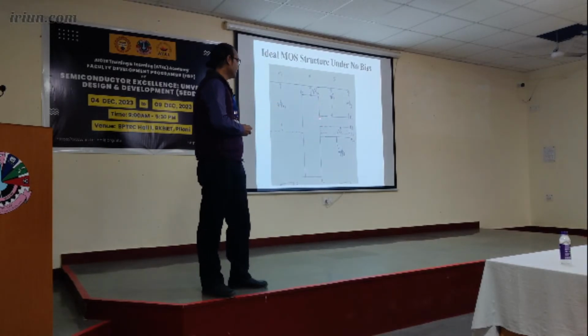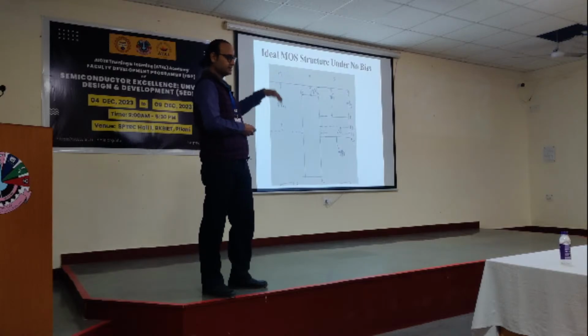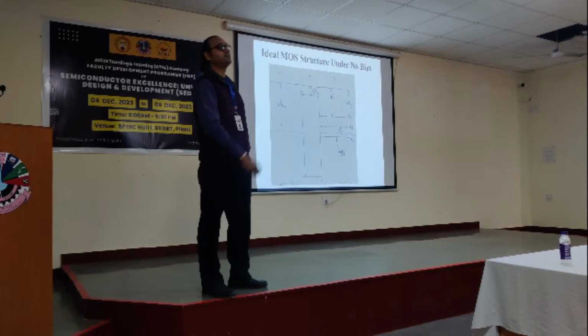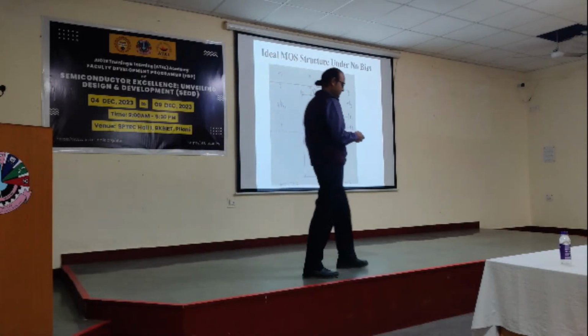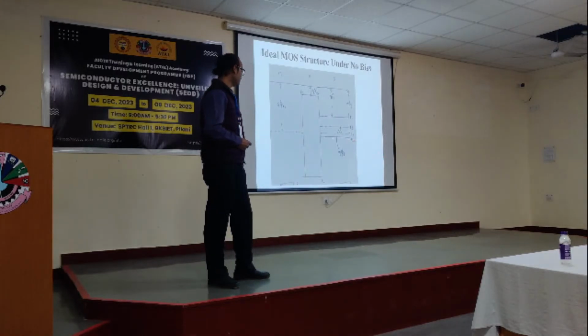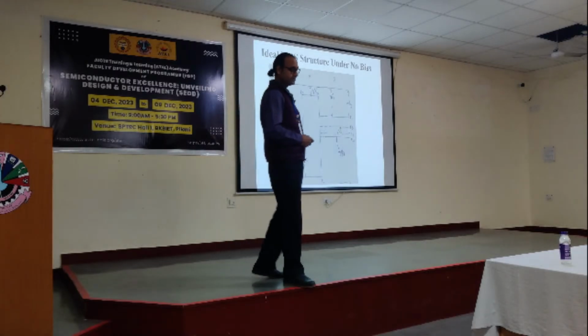We know very well that whenever the electron concentration changes, the band will change its position. Suppose there are more electrons here. Now what will happen? The band will come down, closer to the Fermi level. Why? Because the electron number has increased, right? And accordingly the gap has to be maintained equally, so the valence band will also bend. In fact, the intrinsic level has to stay in the middle of the conduction and valence bands, so that will also bend.